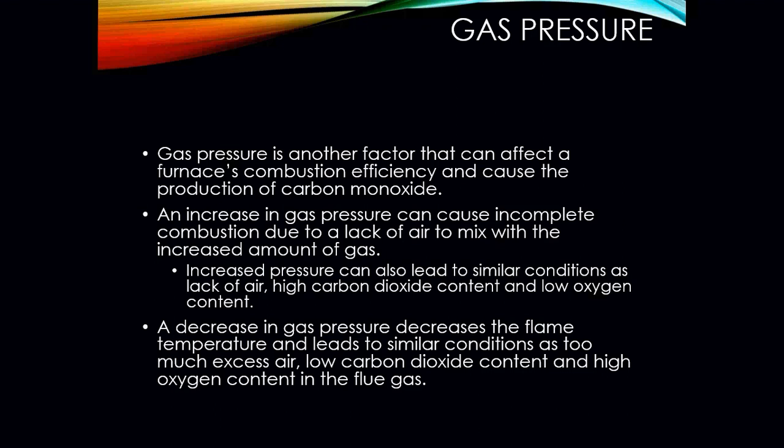Okay, gas pressure. Gas pressure is another factor that can affect a furnace's combustion efficiency and cause the production of carbon monoxide. An increase in gas pressure can cause incomplete combustion simply due to the lack of air to mix with the increased amount of gas. Increased pressure can also lead to similar conditions as lack of air: high carbon dioxide content and low oxygen content. A decrease in gas pressure decreases the flame temperature and can lead to similar conditions as too much excess air: low carbon dioxide content and high oxygen content.